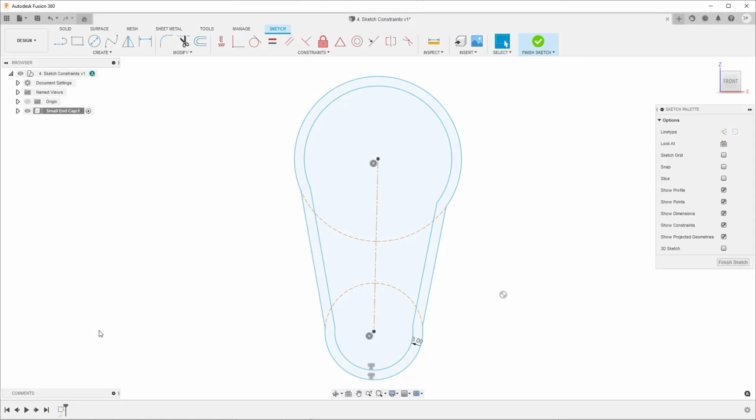As a best practice, you should attempt to constrain your sketch so that it aligns with the origin. By doing so, all other sketches and components you create will have a common reference point, helping to build more unified, consistent, and manageable designs.